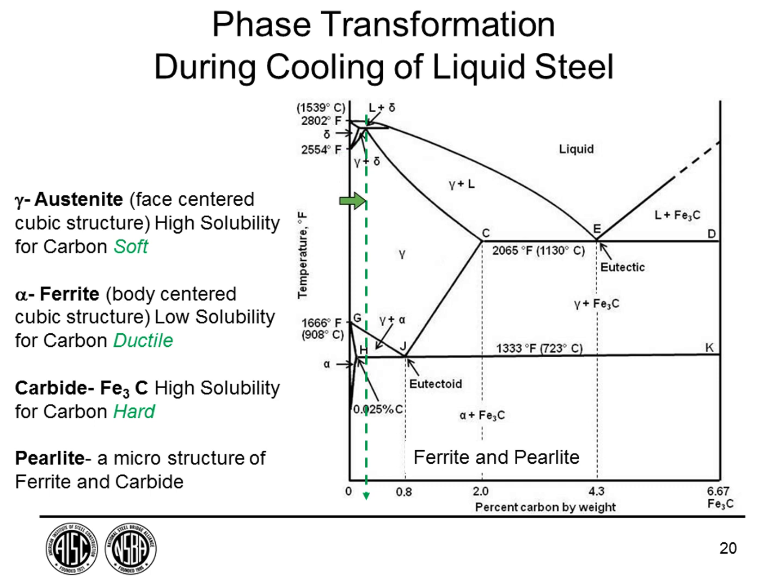This is the typical chemistry of a structural steel, with carbon contents of around 0.2. This is typically where we are, and so we're going to be starting out here, rolling it in the austenite range. When we get down into this range, the actual molecular structure of the steel will start to change. Here it's a face-centered cubic structure. We start forming in here the alpha phase, which is a body-centered cubic.